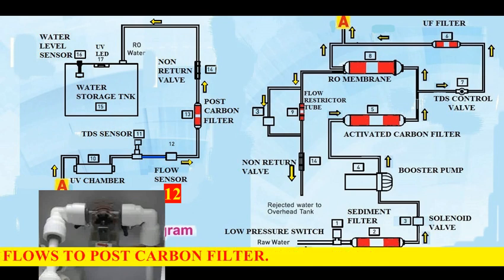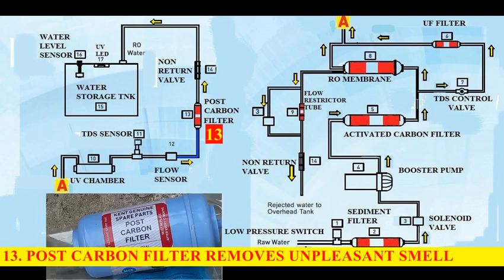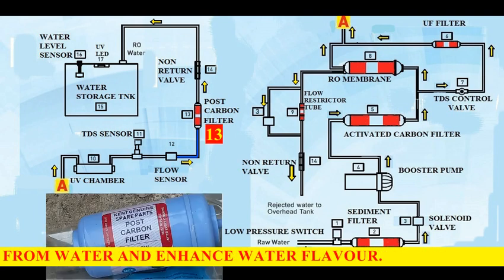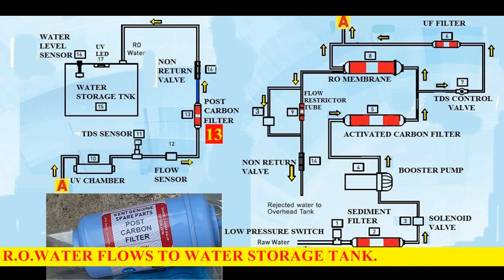Via flow sensor water flows to post-carbon filter. Number 13, post-carbon filter removes unpleasant smell from water and enhances water flavor. From post-carbon filter, via non-return valve, R.O water flows to water storage tank.